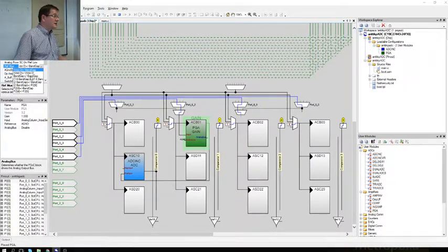There are different settings. You can run it as band gap plus minus band gap, which means the 0 or analog ground level would be at the band gap, and then the operating range for the analog circuits would go from 0 to 2 times the band gap.